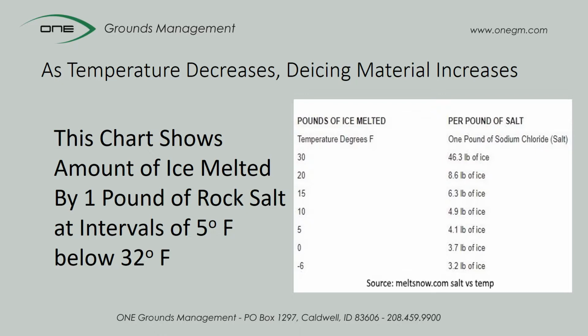There is another reaction between water and de-icers that we must consider. As the temperature of water in the solid state decreases, the amount of de-icer needed to melt that ice increases. This is why we need to understand what the surface temperature is. It is a factor when calculating the amount of de-icer needed to keep a surface safe. Our next training module will show the new additions we have made to our phone app that will calculate these amounts for us, given the surface temperature and the surface area to be treated.